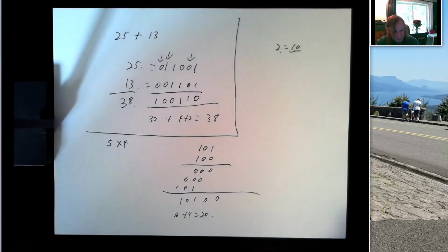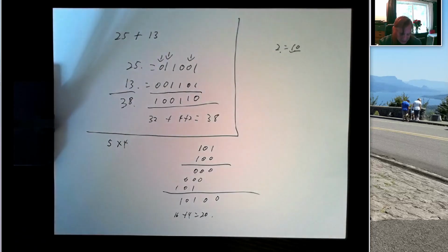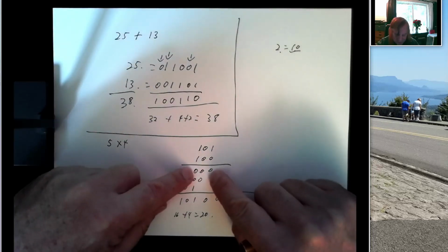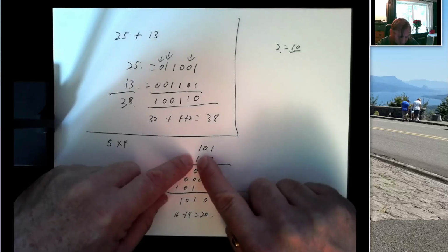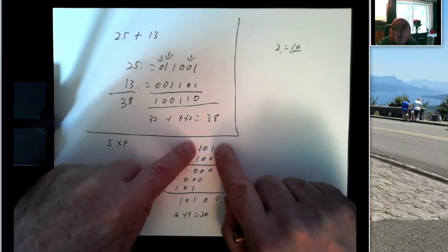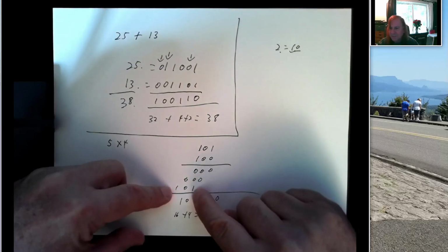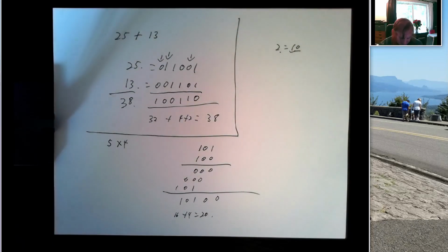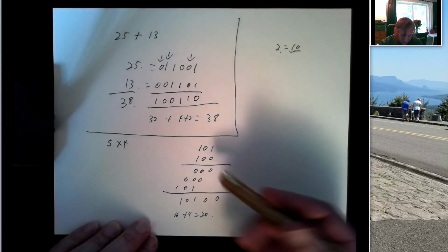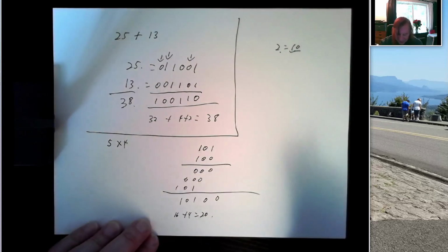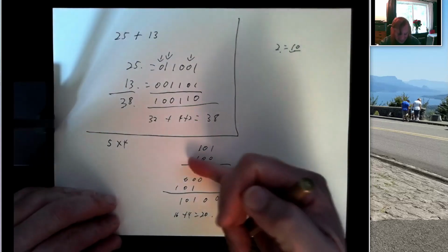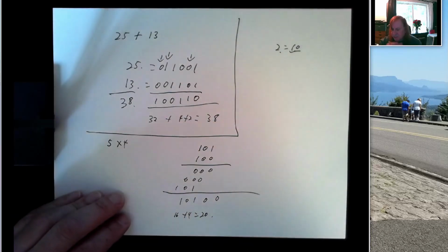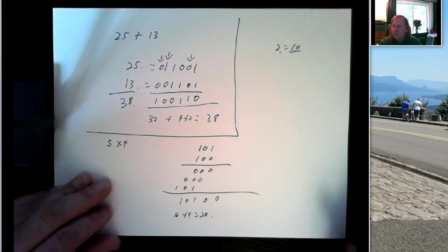That's 5 times 4. It's easier because if we have a 0 here, multiplying our number by 0 leaves us with 0. If we have a 1, multiplying this number by 1 just takes this number and puts it down there. So it's an add and shift, but the add part's not really very significant. It's really just write this number down in different positions, and then at the end go through and add all of these. And so multiplication works the same. We can also do division, we can also do subtraction.